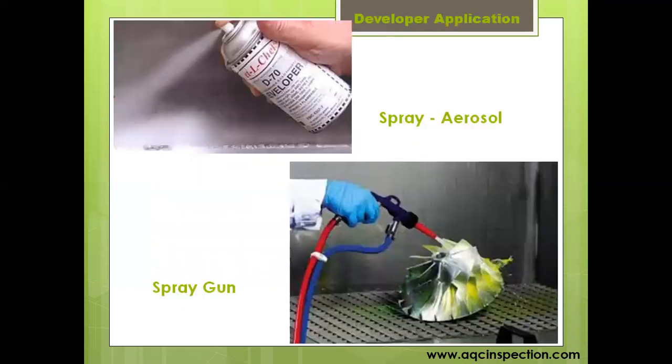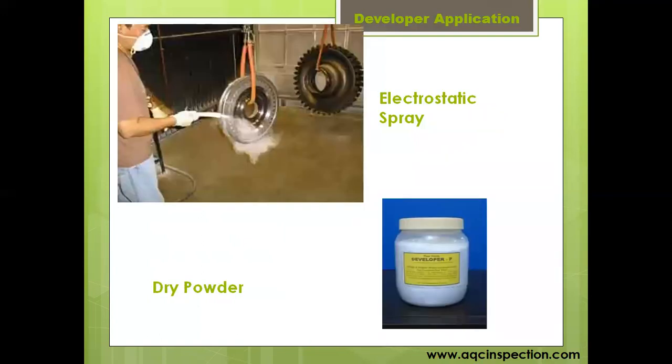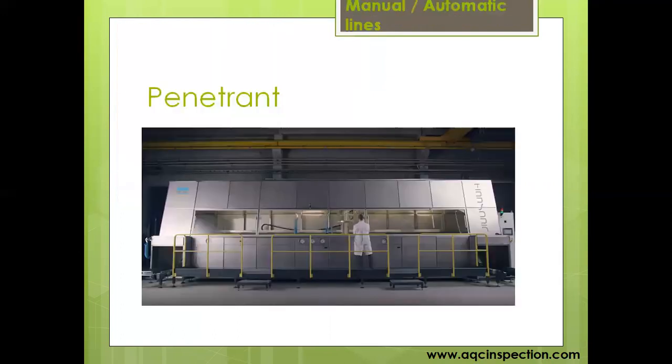A few pictures of developer application are given here. Aerosol can spray, spray gun, electrostatic spray, or dry powder application. Also, manual or automatic penetrant testing lines are available. A picture of such a working station for liquid penetrant testing is given here.